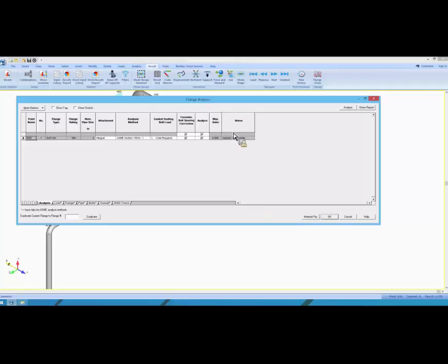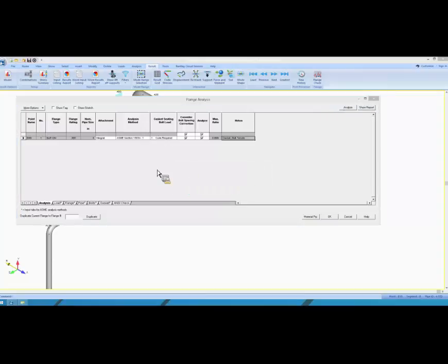And as soon as the analysis is performed, really quickly, we can see the max ratio given by this report for the ASME Section 8 Div 1 is 0.899. As the ANSI flange check is basically a bit more conservative, we can see that maybe using the correct data in the ASME Section 8 Div 1, the flange is actually passing all the checks, and this max ratio is from among all the bolt loads required, or longitudinal hub stress or radial stresses. So let's have a quick look at the report as well.